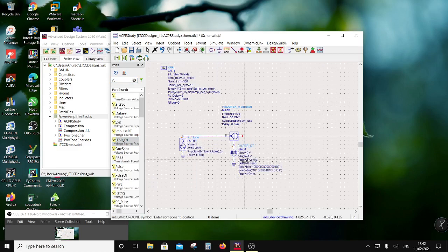so what it needs is certain taps. I can put it in binary, or I can put a number here, and then it needs a seed, which is a start value. Okay, I can put any number here, right? Start value. Then I need here rate, so this rate will be bit rate. And then I want this to be a bipolar signal, so -1 and 1.